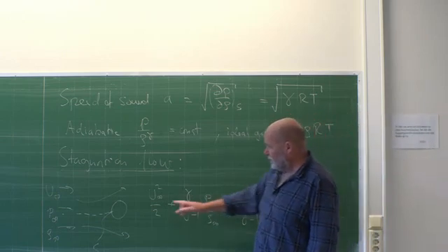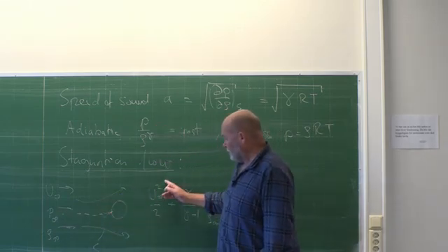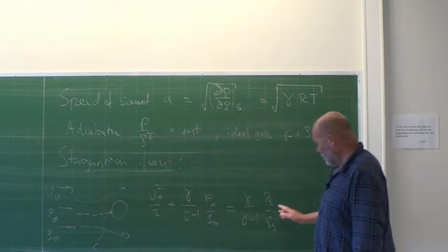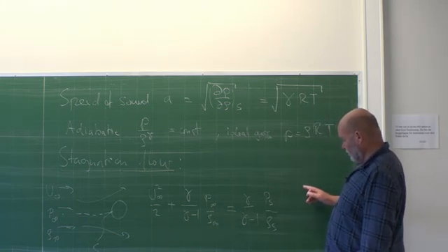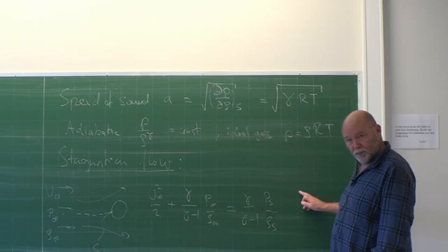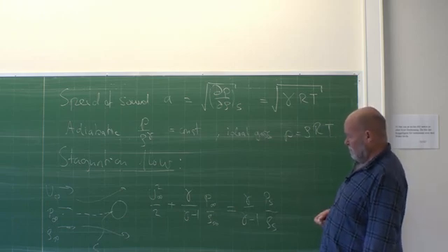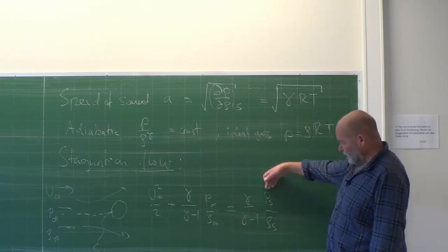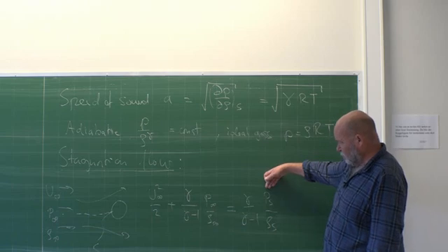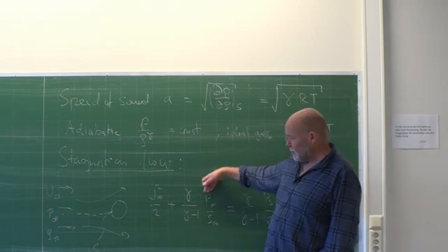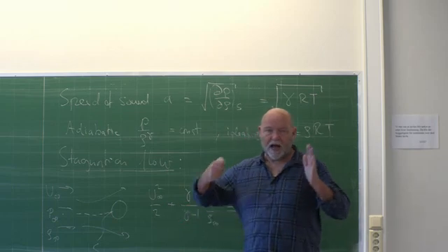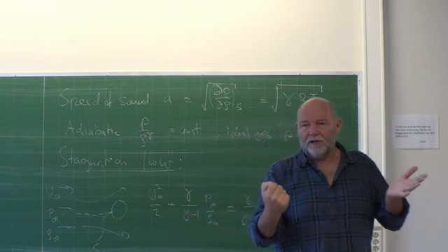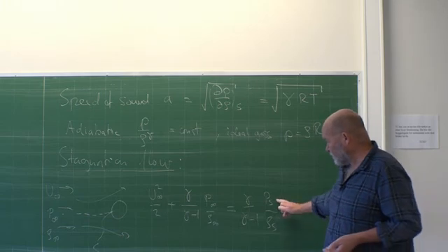Well, then the situation over here doesn't have a velocity. But this one has a velocity, so then plus u infinity should be on this side. And then also you see something strange. Here you now have the stagnation pressure. It will equal the surrounding pressure plus the dynamic pressure. Makes sense. Stagnation pressure will increase.